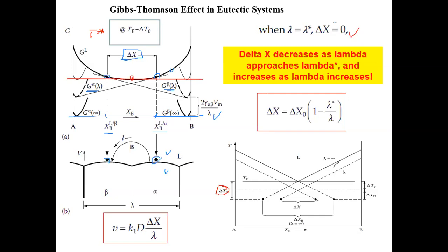As we showed before, when you change lambda, you're changing the effective melting temperature, and you're changing the degree of supercooling that the nucleus feels. So that is basically the setup. Suppose that we have lambda goes to infinity. In this case, as we said many times, we have just a bulk form. The system is very happy and actually reaches the theoretical melting temperature, which is TE, right?